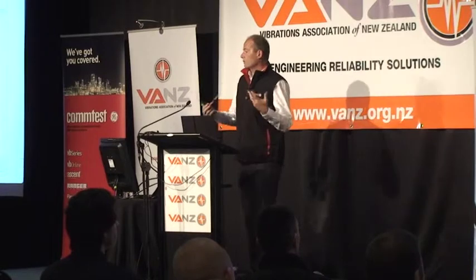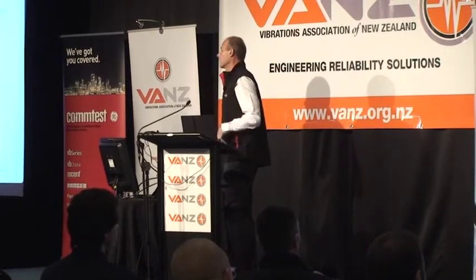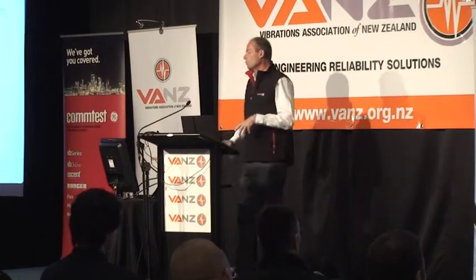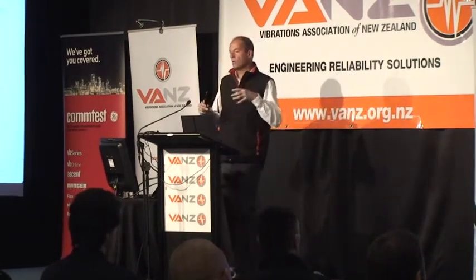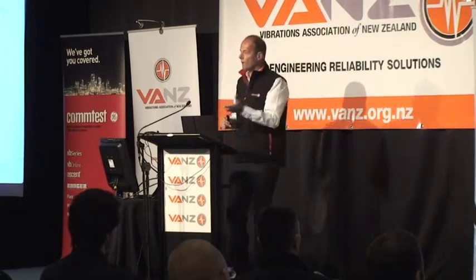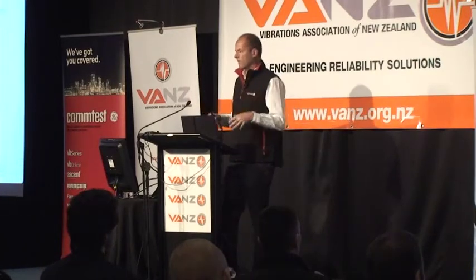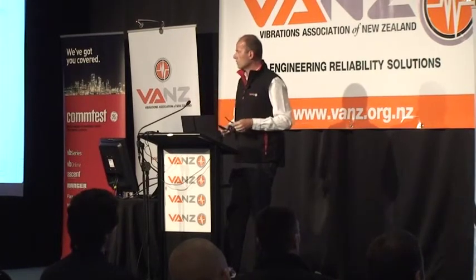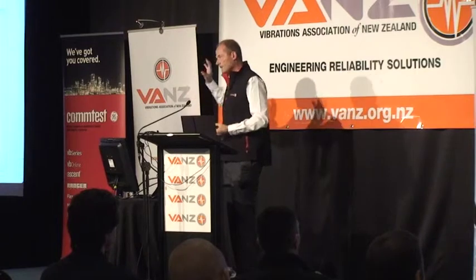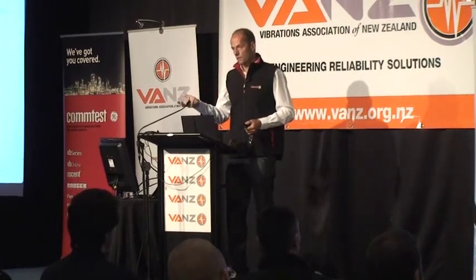There's lots of tests you can perform on electric motors. In addition to just taking vibration readings, we can examine the windings, the connectors. We can examine the supply of the voltage to the motor. Insulation, I forget whether I said that. So there's a lot of tests you can do that examine exactly what's happening with that motor, even detecting some of the mechanical properties of the motor